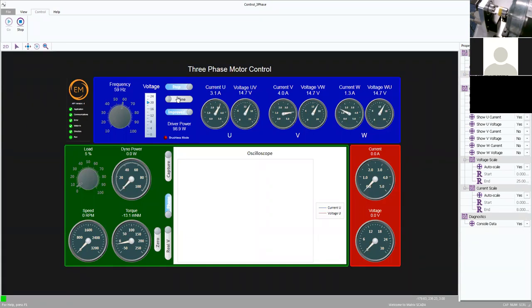And there's a technique called the 6-step driver system, where you're able to then change the logic, if you like, or the power output of these 3 driver systems to create a 3-phase system. And what we do is we use pulse width modulation to create a sinusoid on each of these outputs.